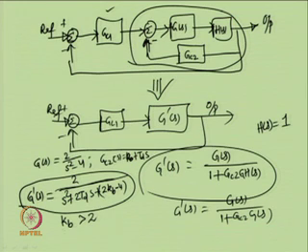So, with proper design of the control parameter Kb, that means when Kb is greater than 2, it is possible to locate the poles of the original unstable process G(s), which has one pole in the right half s plane, so that both its poles are in the left half s plane.